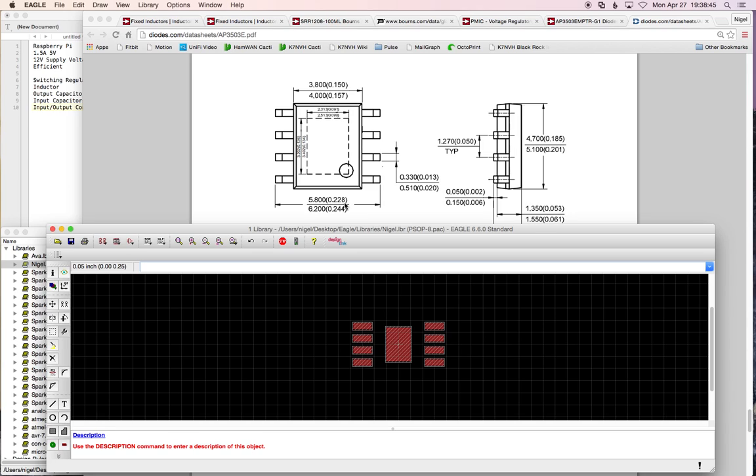So now the question is where to place them horizontally. And so in this case, they say that the total width between the end of the pads, the end of the pins side to side, is going to be 0.244, i.e. a quarter inch. I'm just going to round up to 0.25. So if we look at our position here, we go from negative 0.20 to plus 0.20. So right now we're at 0.4 wide. So we're actually a fair bit wider than we need to be. But that's okay, because we made our pads extra long.